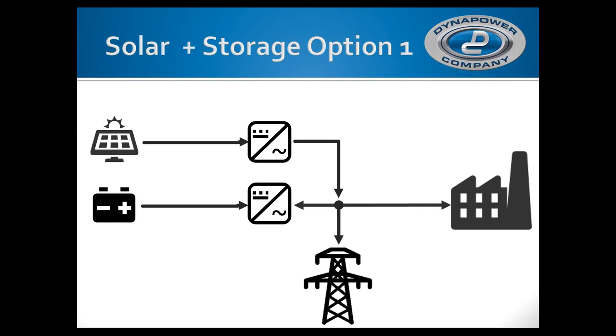So when we look at it from an engineering perspective, the first thing we want to look at is what is the actual load that we're going to have on this islanded microgrid. That becomes the smallest size of the battery inverter that you would have. If there are any questions, again, please jump in.